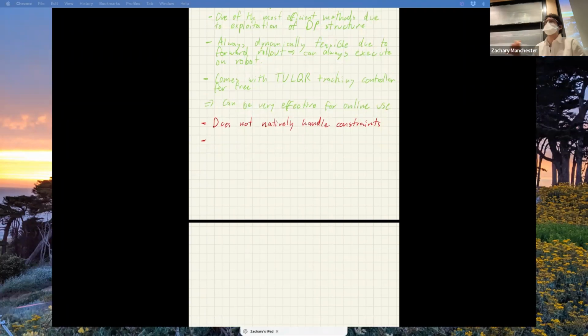The other side of this anytime dynamic feasibility thing is that these methods don't natively support what's called an infeasible start, or infeasible initial guess. What that means is I can't just make up a random state trajectory as a guess that doesn't obey physics, which you can do with the other methods, these collocation methods.